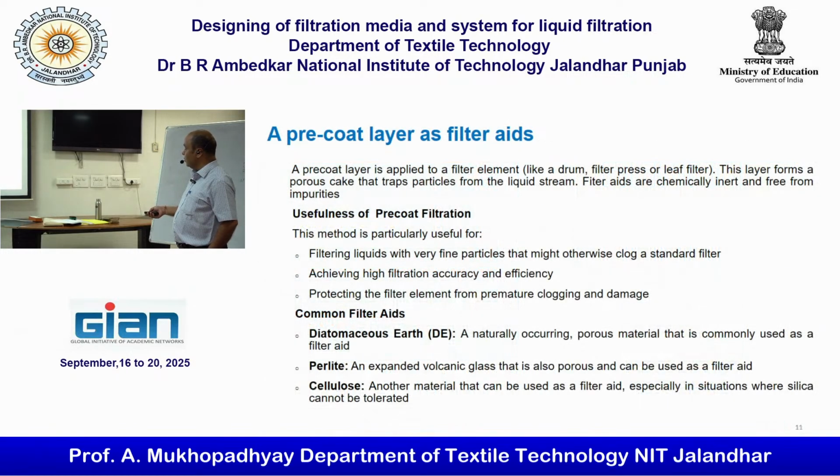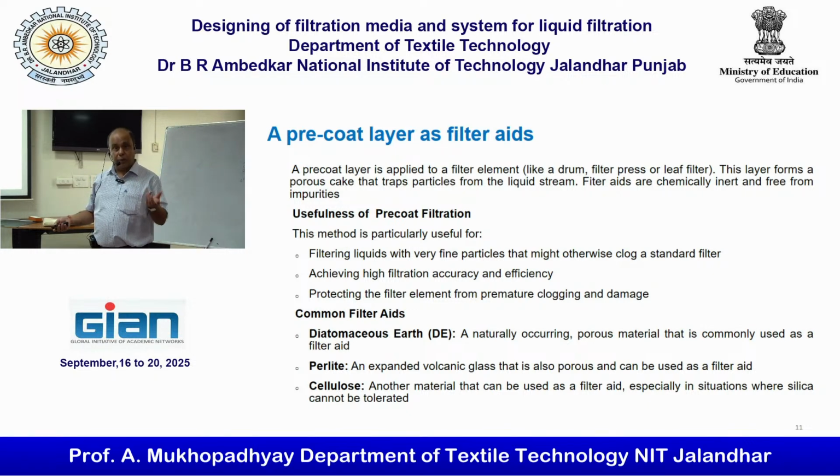I am just skipping a few slides because a lot of slides are there. Cost of filter media also matters, because in certain cases the cost is low. That is why in a number of cases oil filters are made out of paper. Although fabric performance will be better, sometimes the oil filter is made out of paper, but with resin treatment, because cost is again one of the important aspects whenever we are looking at a particular kind of filter.